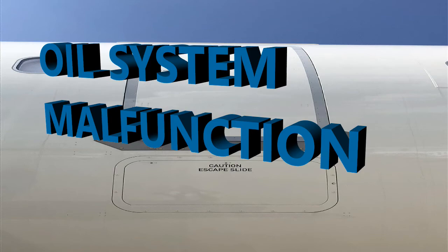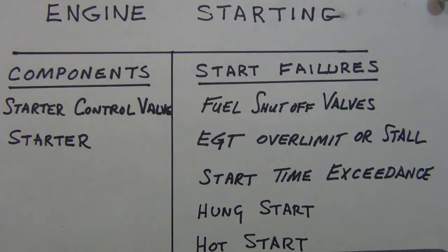So here you've got the engine panel 115 VU. You select the mode selector switch to crank. Okay, there's also on the overhead 22 VU, you have the control and indication, the CTL and IND panel. There's the push button for the engine manual start. Okay, that's the internal engine fire as far as what you do.